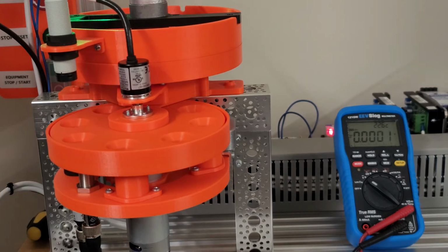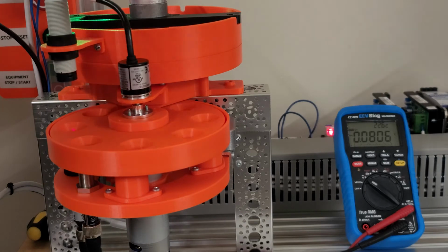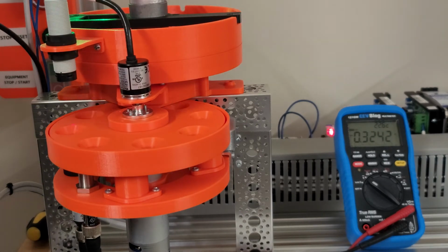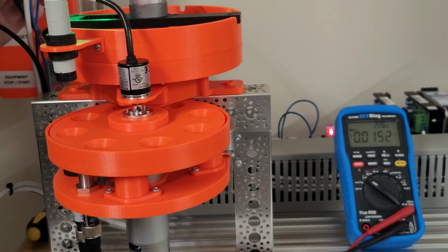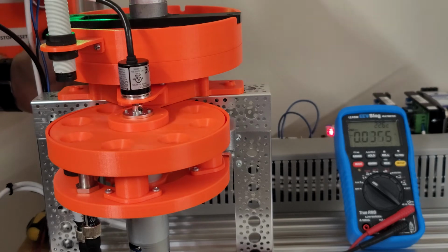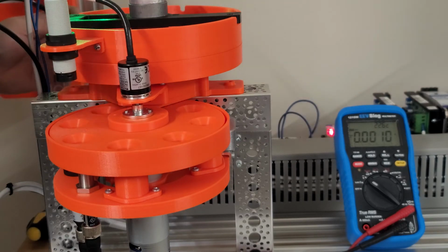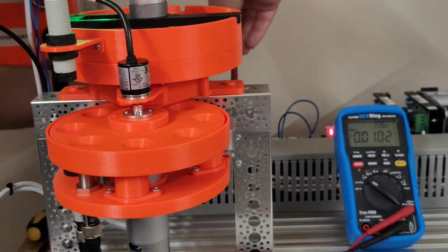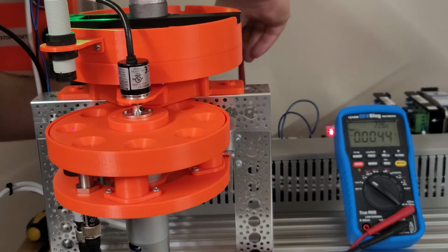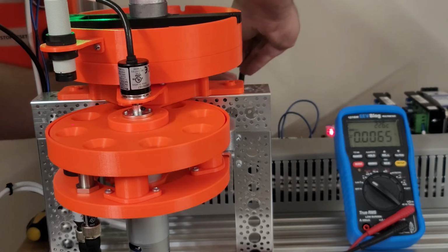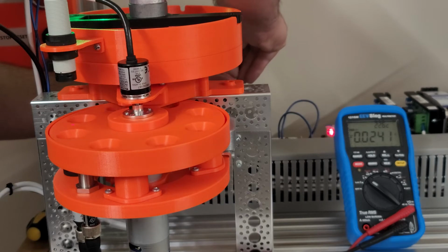Okay, both motors are running. So the first thing we'll check, I have my multimeter already set to DC voltage, and we will just check it with the common on the output card. It's going to be hard to see what I'm doing, but you should be able to see the display on the multimeter. If not, I'll read it out just in case the glare is a problem. So we will put this here, and we want to check it against the common.